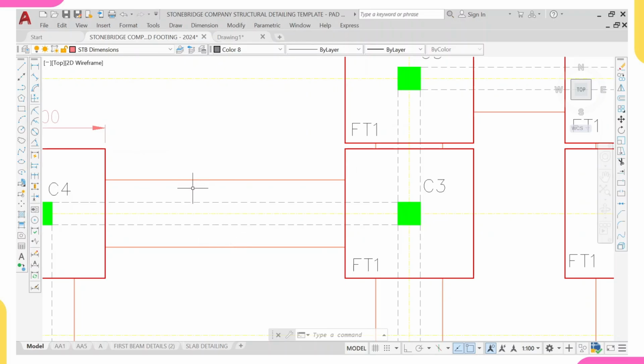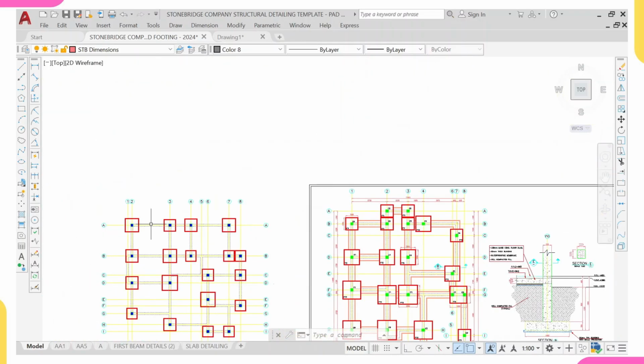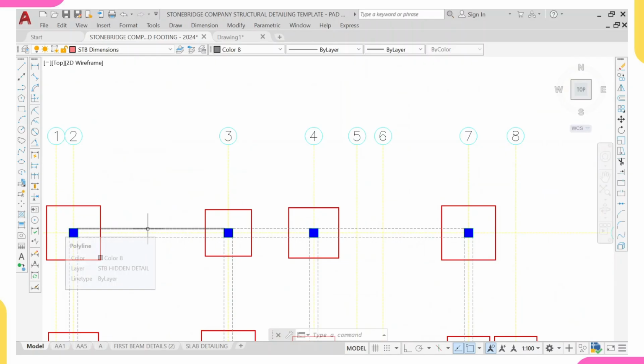Do you understand? Because of the bricklayers, where they will stand, we will offset 225. So this whole line now, from here to here and from here to here, is where the bricklayers will stand and lay the block. From here to here is our block width. So what I'll do now is come over to my drawing and start offsetting 225 by 225.